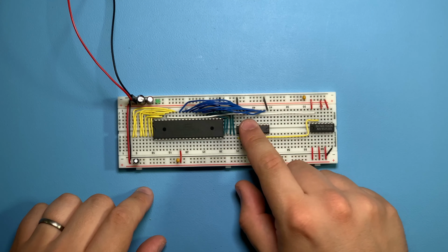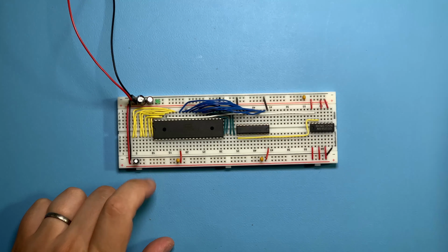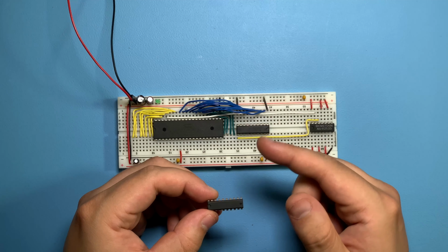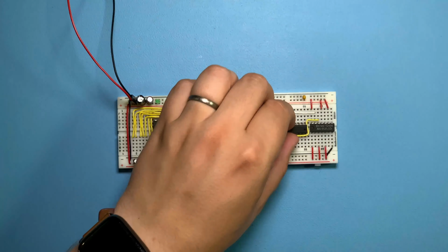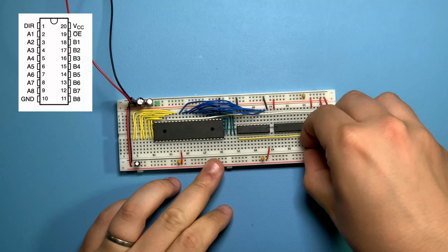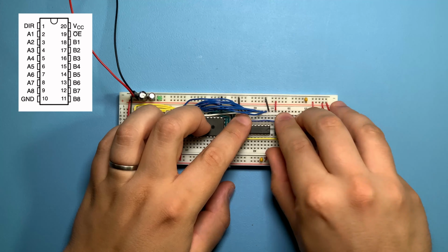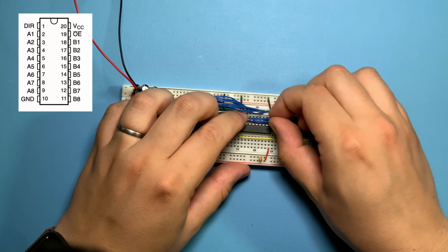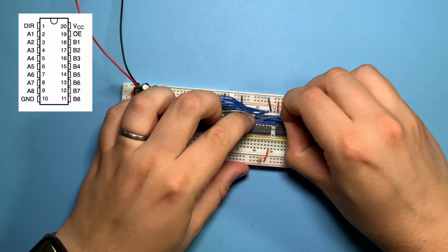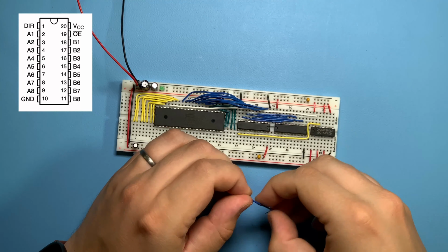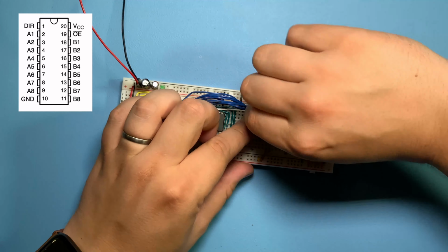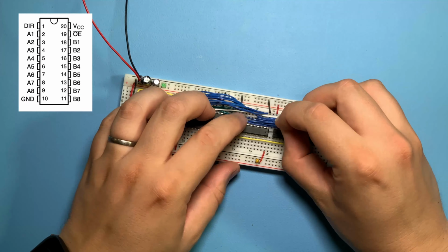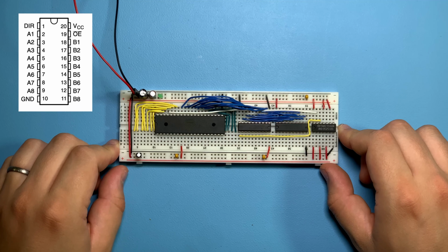Okay, so now we have all the address pins decoded, and we actually need the data pins here. So for this, the datasheet recommends using a 74245, which is the chip that I have here. On this chip, we can select the direction that we want it to go, so we can put it the right way around. So it needs power and ground, and then we need to transfer the data pins over. So that's all the data pins.